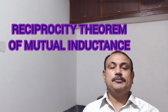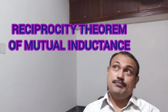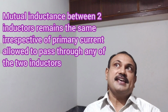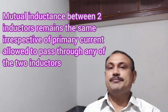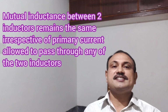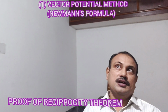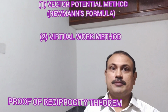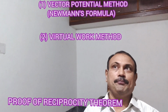Well, reciprocity theorem of mutual inductance. We have seen that the mutual inductance between two inductors remains the same irrespective of primary current passed through any of the two inductors. Already we have seen. Now we can prove this reciprocity theorem in two ways: by vector potential methods and by virtual work methods. The vector potential method, which generally we say as Neumann formula.